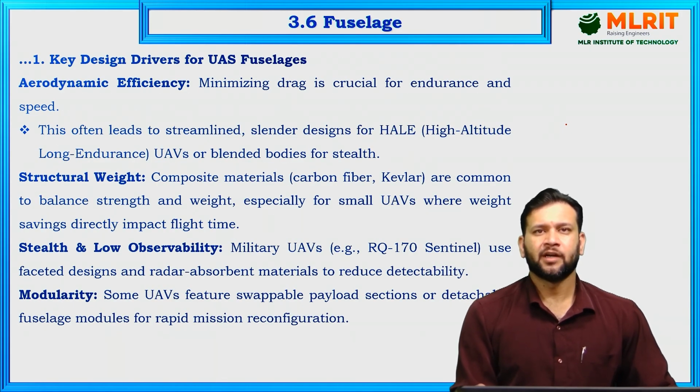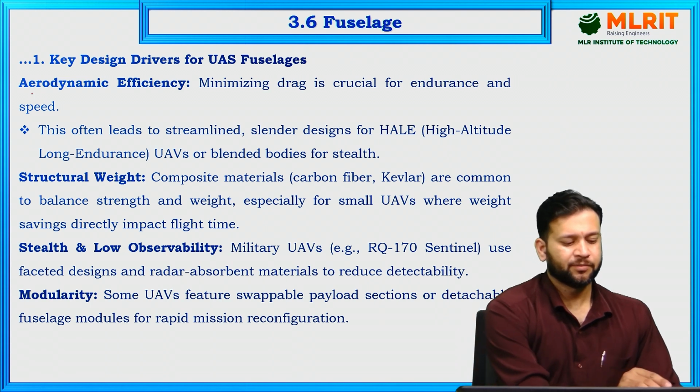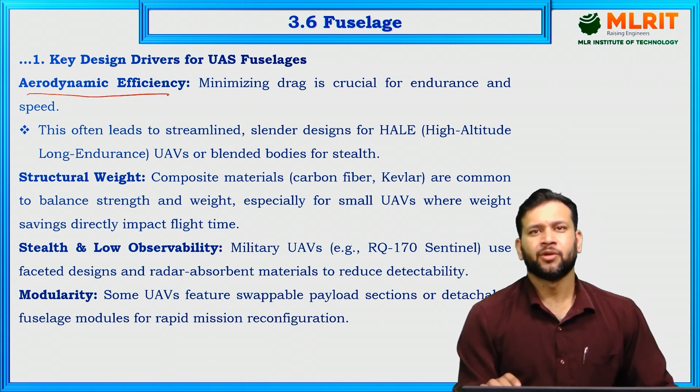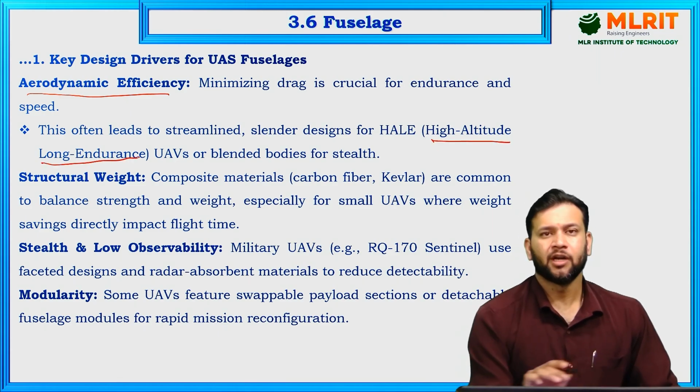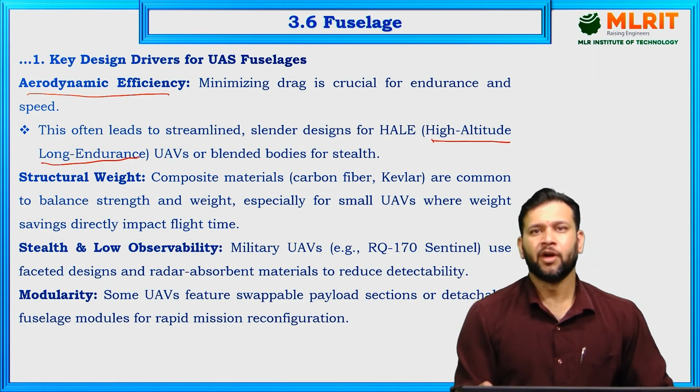The key design drivers for unmanned air vehicle fuselages are aerodynamic efficiency, which ensures minimizing the drag because drag is crucial for endurance and speed. This often leads to streamlined, slender designs for high altitude, long endurance unmanned air vehicles or blended bodies for stealth.